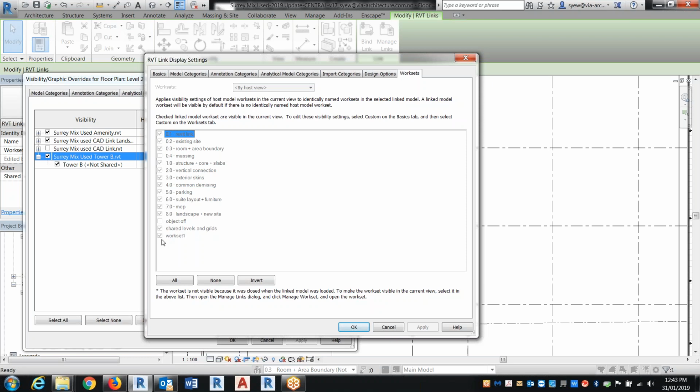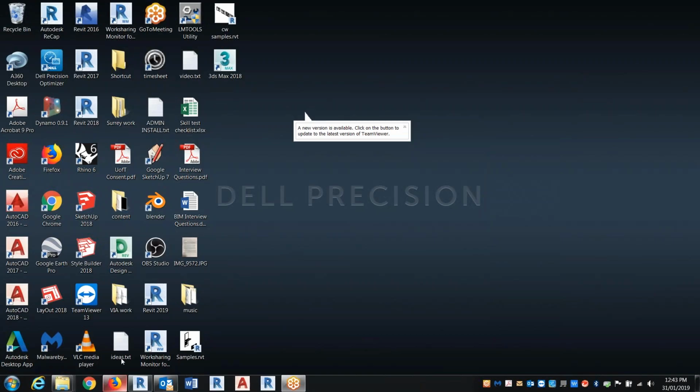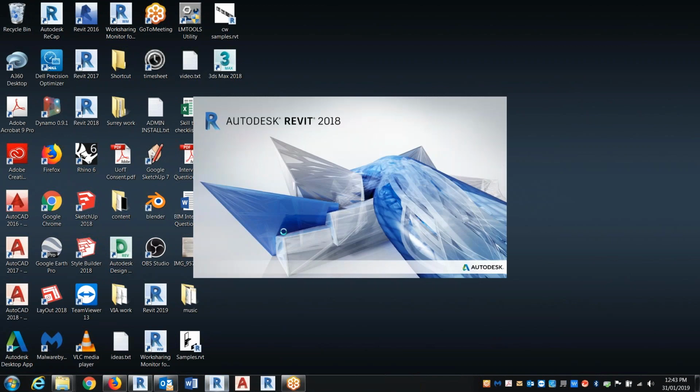So what I'm going to do here is that, okay, for example, here I don't think I have any consultant. Maybe I should create another one so that I'll show you what I'm talking about, because it's kind of hard to display this since I already have that. Maybe I should try the dialog version so that they have a workset. I'm going to link their model into mine, and then I'm going to create my own workset, and just say I want only to show this, and then do not show the other. You could do that with workset.